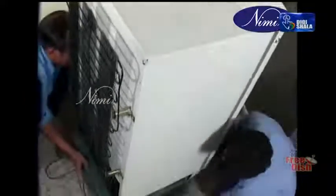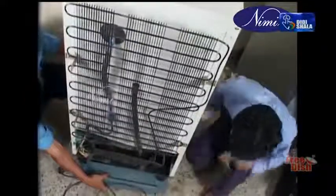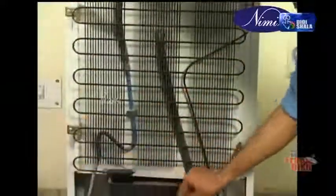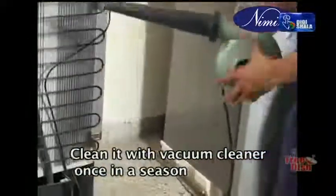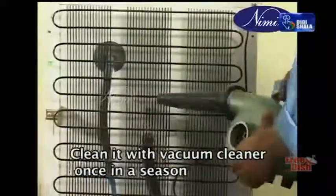If the machine has an open condenser installed on its backside, clean it with a vacuum cleaner or air pressure once in a season.